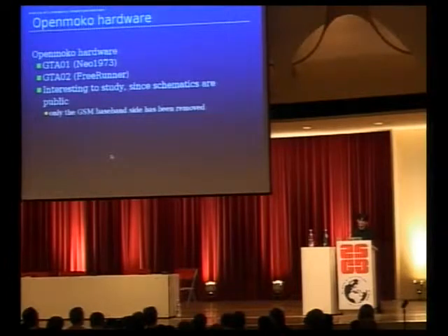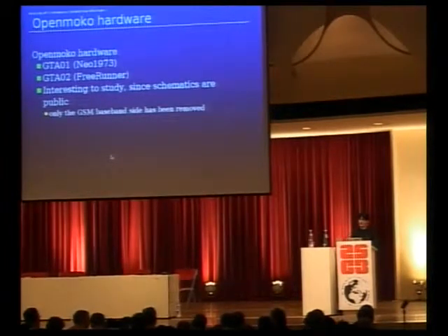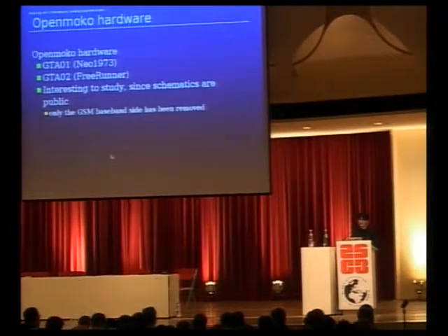Full schematics, in quotes, well, detailed schematics, but the GSM baseband side cannot be there because of the closed nature of particular commercial entities in the semiconductor business for mobile phones. But if you want to understand the functionality of the phone, the baseband side, you just look at it as a modem. It connects to a serial line, you get analog audio data in and out, and that's about all you need to care about.